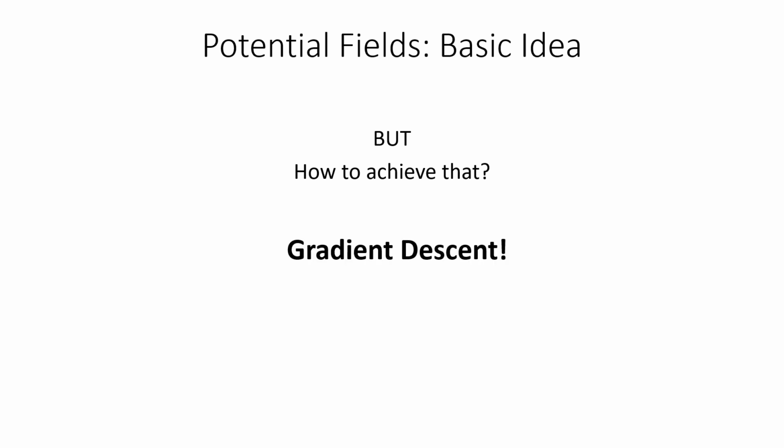So this whole exercise is to find the highest and the minimum potentials. But how are we going to make the robot move from the highest potential to the lowest potential? How are we going to achieve that? That's the bigger question. So possibly what we can do, we can take the gradient of the whole potential, and then we can ask the robot to descend from the highest potential to the lowest potential along that gradient. And that would be what we call the gradient descent method.